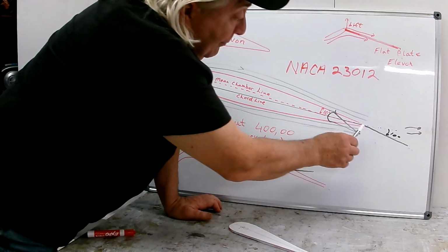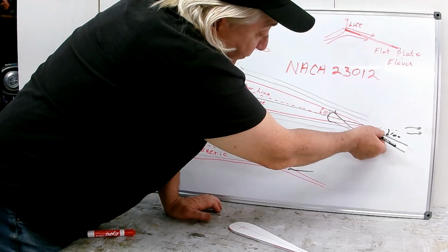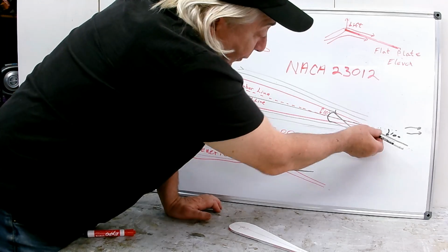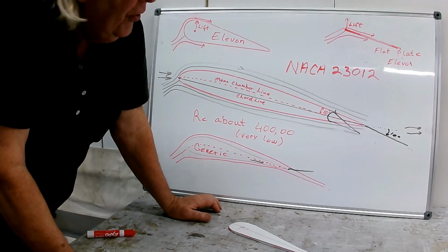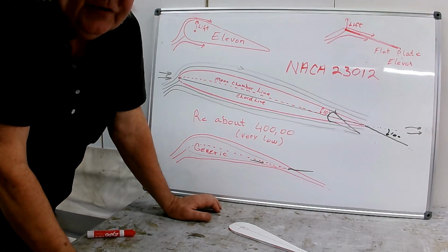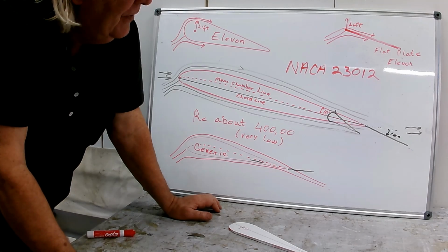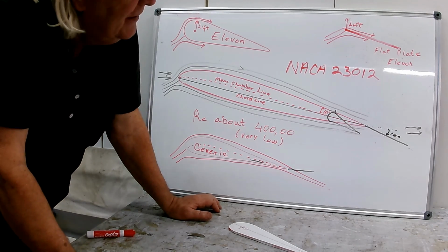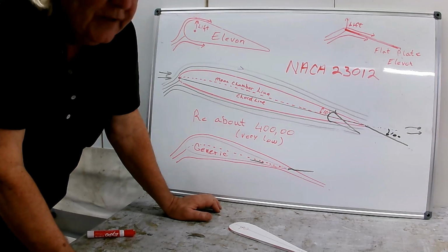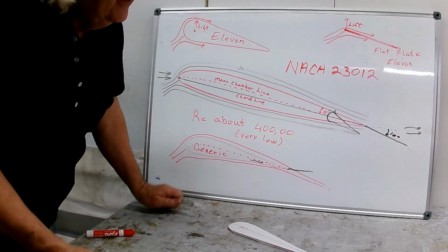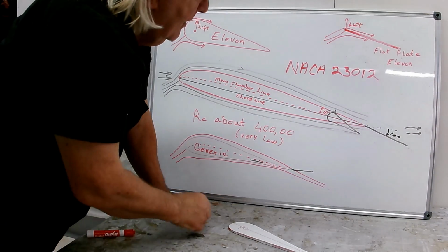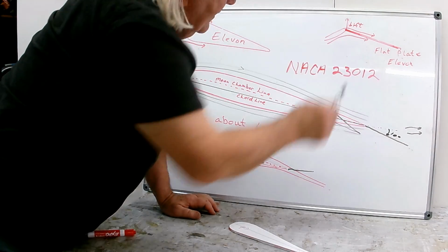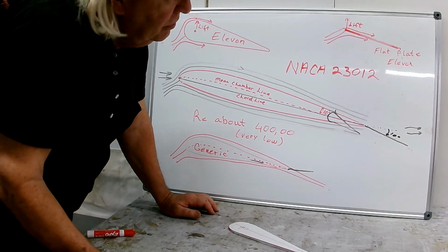So with the flat plate back here, we have 10 degrees of throw available before we cause any discontinuity. We're not causing the flow to do anything weird. We're not asking it to do anything unusual mathematically until we have 10 degrees of deflection in that control surface. You're saying, oh, okay, Raul, then you're really not generating any lift here. And I said, well, maybe.